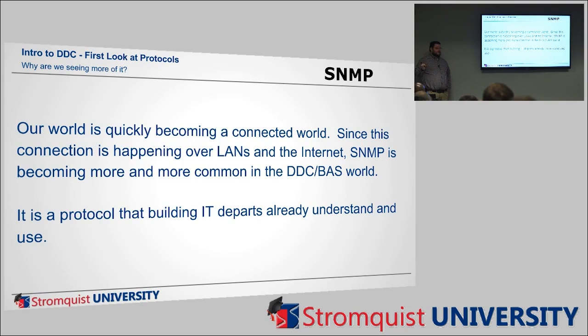So if you're a contractor and you're having trouble getting on a network, contractors and IT people don't always see eye to eye, and the IT guy doesn't think you know what you're doing and doesn't want you anywhere near his stuff because he's security conscious. But he knows what SNMP is, so that's why it's become more popular, because I can say, I can give you this information this way, and he goes, well, I understand that, that's fine, send it on.